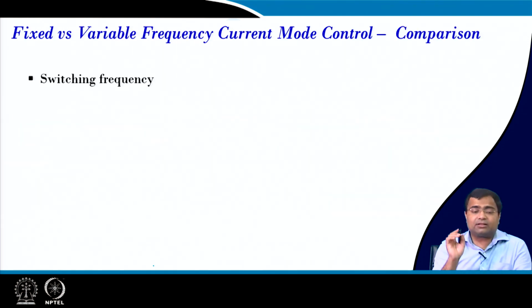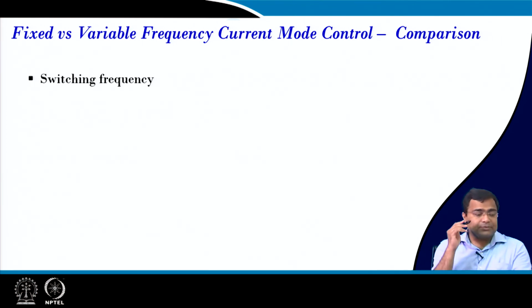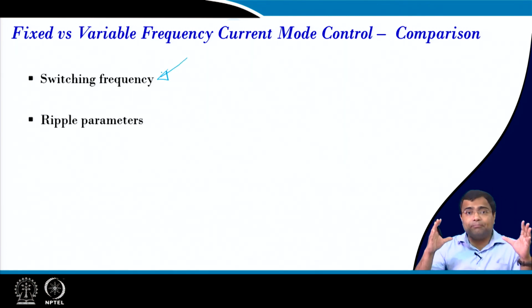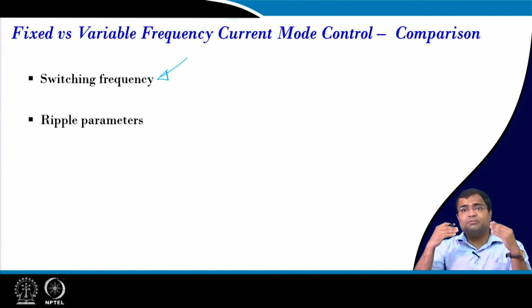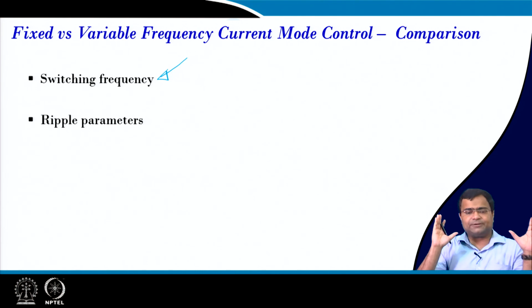But in this particular lecture we want to recapitulate these modulation techniques which we have already discussed, but we want to emphasize that variable frequency control inherently suffers from frequency variation. But this is the starting point of digital control, where I will show you that by means of a digital loop or maybe a counter you can very effectively control the switching frequency.